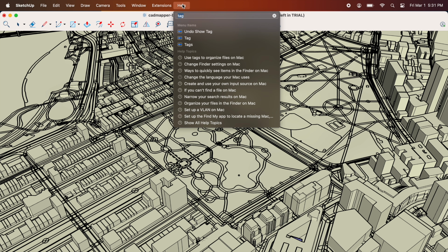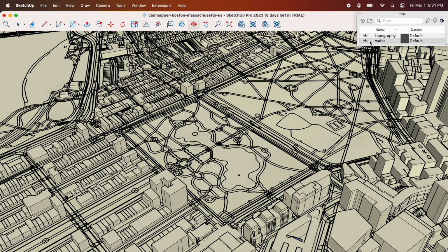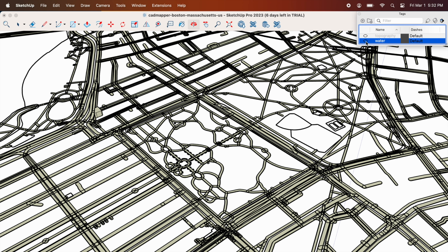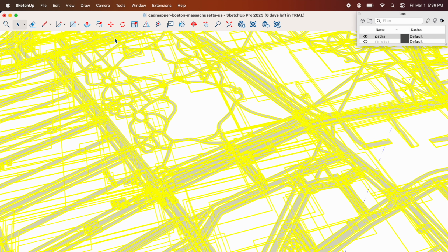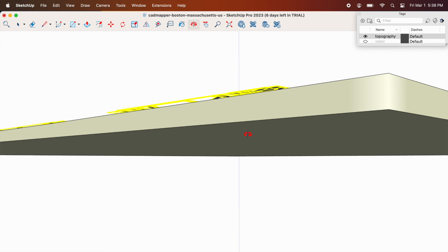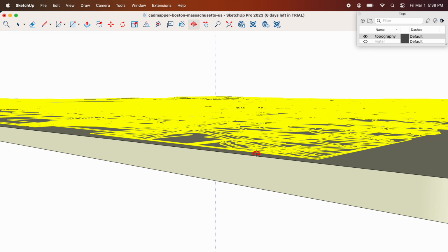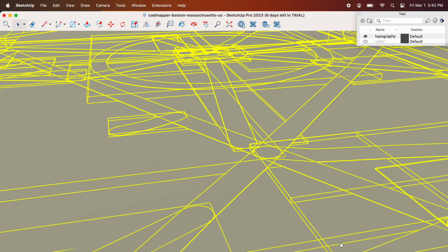Now we have to open the SketchUp file tags, which are essentially like layers. We're going to change the visibility so that we can only see the layers we want to extrude. Keep on paths, minor roads, major roads, and highways. You shouldn't be able to see the topology anymore. Now select all and then raise it up 0.5 millimeter. If you turn the topology on again, you should be able to see that everything is slightly hovering over it. Now you might want to explode the sections before the next step if you end up having issues.